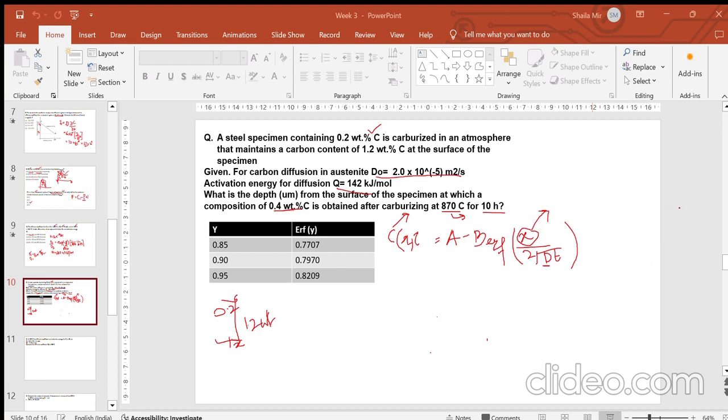For example, lead and tin have high melting points individually, but when they form an alloy, they have a very low melting point. So they form a eutectic point. The eutectic point represents an alloy or a mixture of phases with the lowest melting point. That is why, whenever you find a eutectic diagram, there will always be a dip in the temperature. So this gives you your eutectic point.